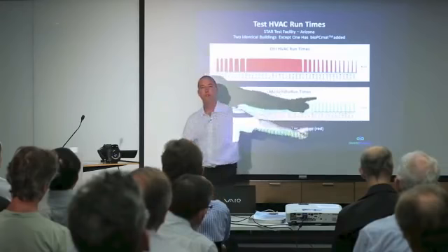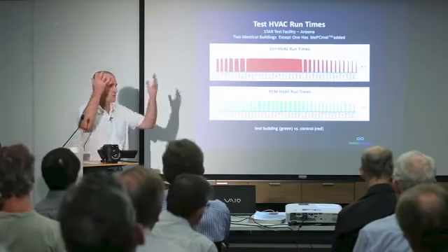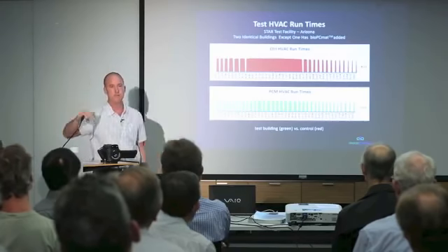Right. And the natural night air can refreeze it, or you can put the building on night purge mode. Just ventilate. Like this Telstra building here, overnight, if they had the phase change through all the ceiling space, they could just put the building on ventilate overnight, push all the night air in below 20 degrees and pre-freeze the building to 20. Then during the day, the aircon only has to pump a little bit of heat out because the phase change is going to absorb all the heat first.